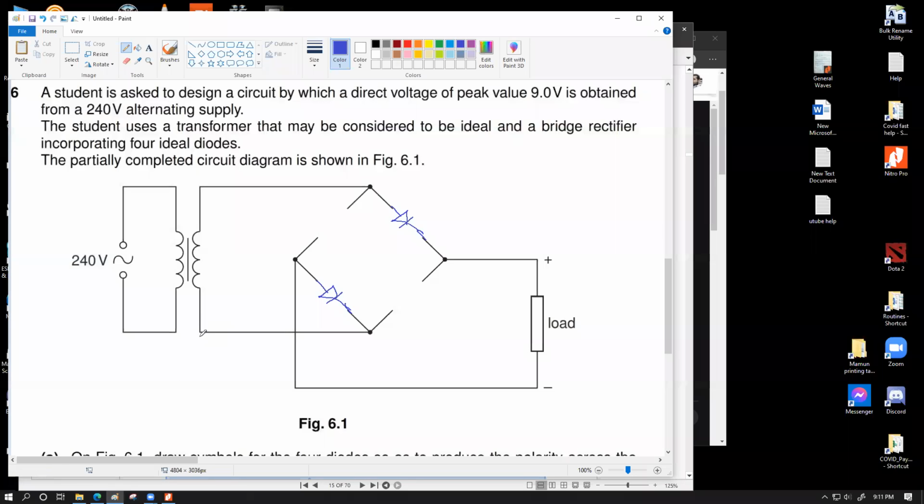And then once again, we'll consider this one. Whenever this has to be a positive end, because this is an AC supply, this is a symbol for a transformer. This part is a transformer. So if this is the high voltage, current should flow in through here, which means this diode should be aimed in this manner so that the high voltage current flows through, comes in here, and then eventually goes back. So another short thing that you can remember is that this positive end that you see should be the end point of two aiming diodes. That also works.